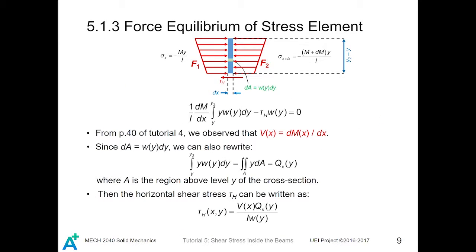If you have read our tutorial notes carefully in the last tutorial, we mentioned a very important relationship, which is the shear force equals the differential of moment with respect to x. That is, V equals dM/dx. Therefore, this term simply becomes the shear force acting on this cross-section.